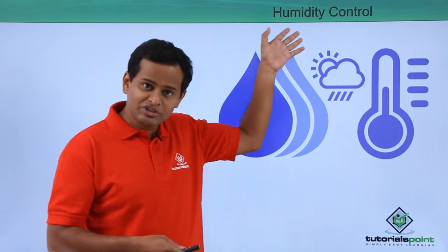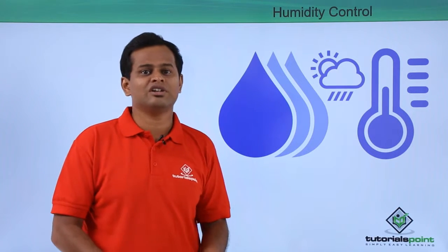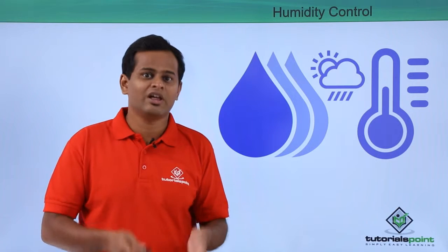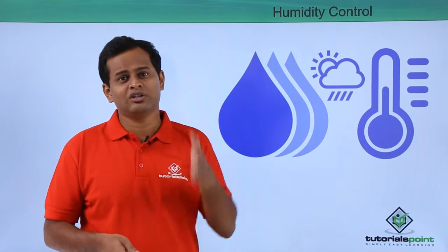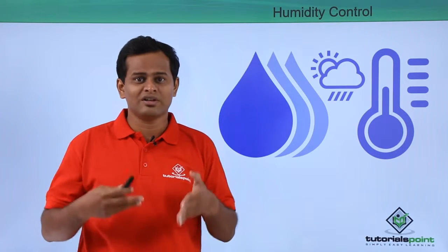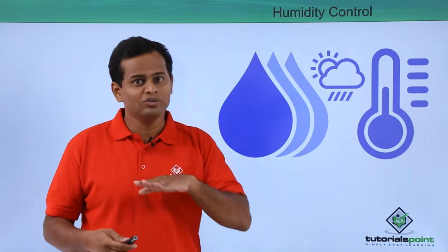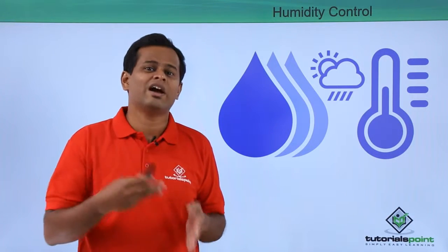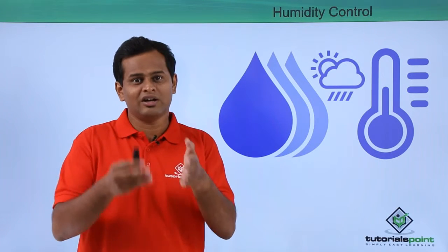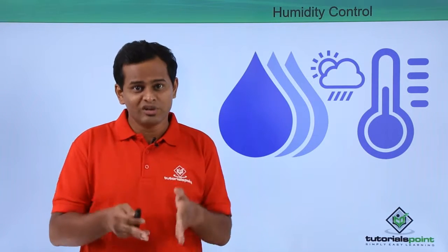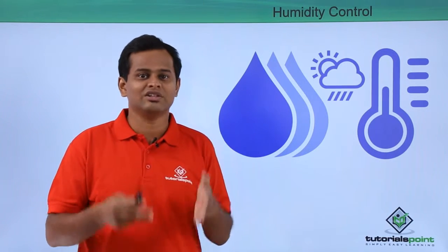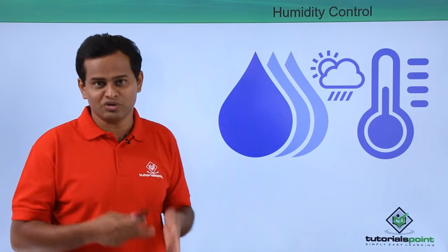With respect to humidity, similar kinds of conditions apply. If we take an example of ferrous items, they are very highly sensitive to high humidity. That is the reason why, if a lot of ferrous items are going to be shipped on the sea, there will be very high chances of them getting corroded. So packaging and other travel conditions and storage conditions for these highly corrosion sensitive materials need to be taken care of from the humidity point of view.